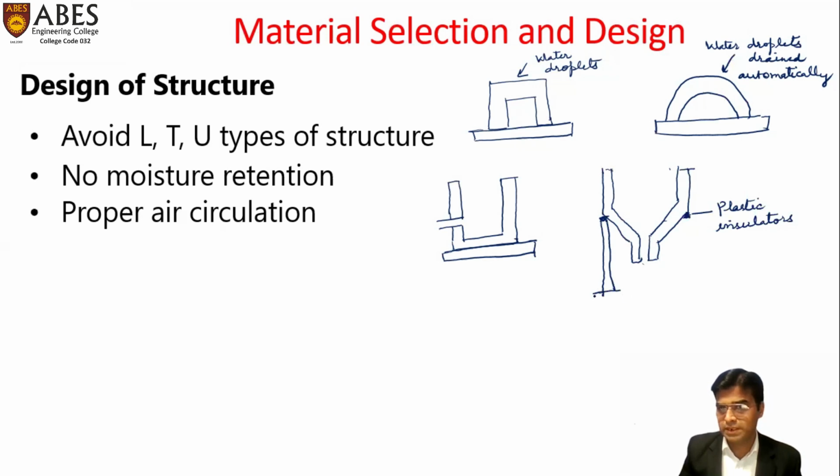So this is the stand. Similarly, these are the legs on which it will rest. So in that case, there is proper air circulation, and this proper circulation of air allows the oxygen to be accessible in all areas, and there will not be differential aeration corrosion.